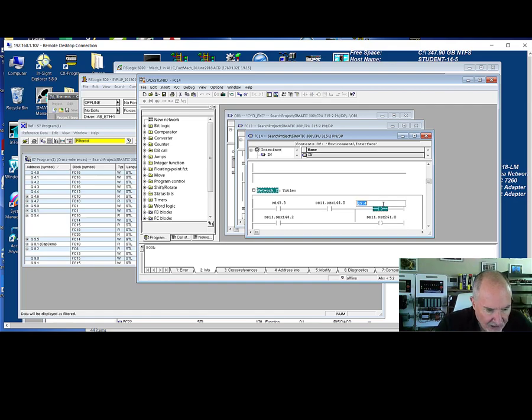So here is an output that is controlled by these different bits. So the typical thing to do here, and you would probably want to take out a nice little notepad, piece of paper, something like that, to write down all these different locations. So let's say I'm approaching this from scratch, and I'm going to get my own little piece of paper out here, and I'm going to write down, in this case, network 2 and FC14. So that is function 14, network 2. And the thing that I'm looking for is what makes Q5.4 operate.